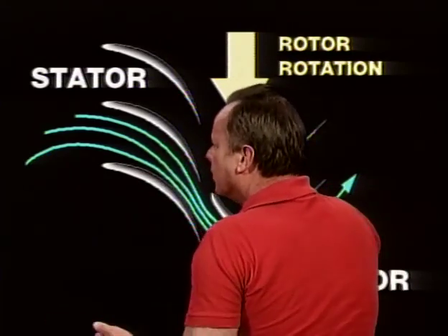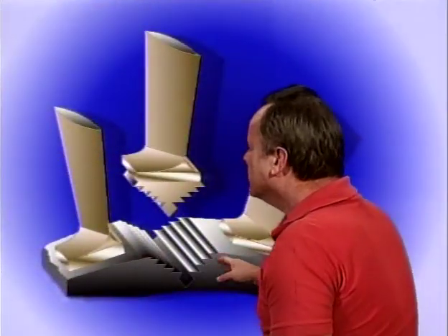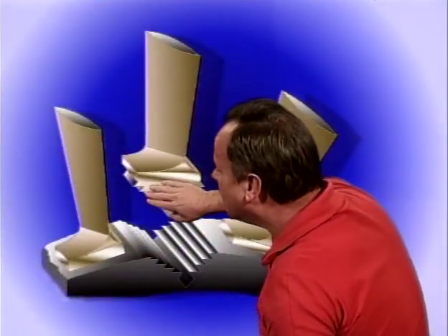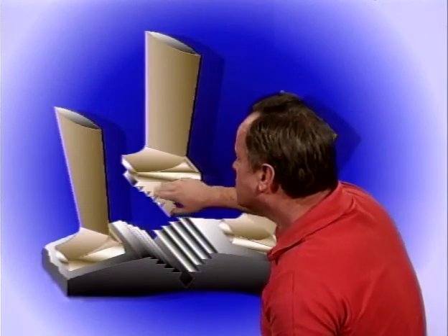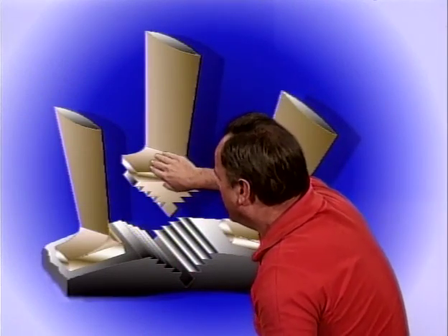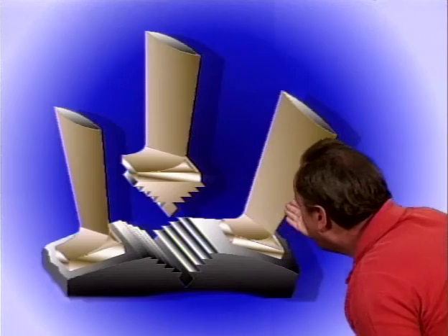A limited number of small nicks and dents in turbine blades can usually be permitted, but only a limited number in the areas away from the root area. So you have to inspect these turbine blades very carefully for damage.